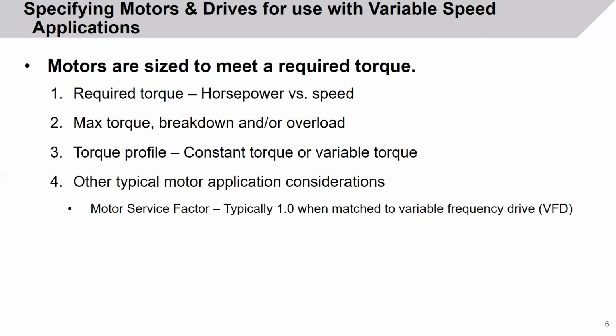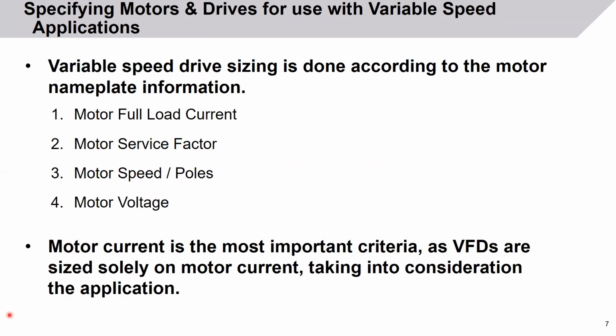One key fact is that typically motor service factor is 1.0 when it's matched to a variable frequency drive. Variable speed drive sizing is done according to motor nameplate information. Number one, motor full load current, most important. Service factor, some companies like to run motors into service factor, so that is certainly a consideration. Motor speed and motor voltage. Motor current is the most important criteria, as VFDs are sized solely on motor current, taking into consideration the application.